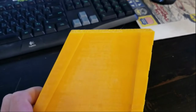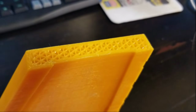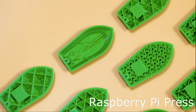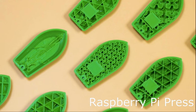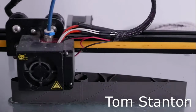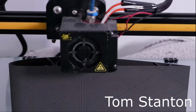Spiral vase printing does not allow for any infill material, which is basically internal support matrix structures that the printer can do automatically to reduce the density of the prints. Infill can significantly reduce the part weight, however is still not efficient enough to produce light parts for RC planes. This is another big advantage of spiral vase. Internal support structures can be specifically designed in order to provide the lightest, strongest part possible to make a flying model.